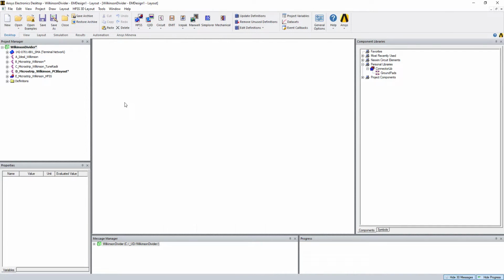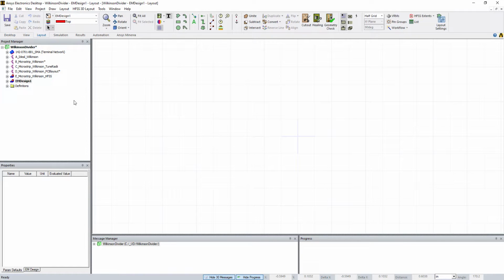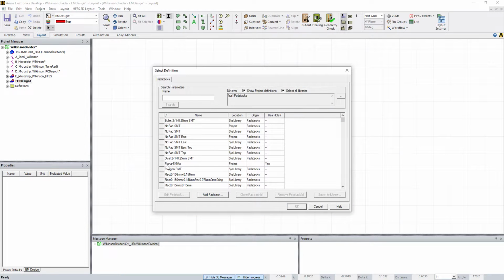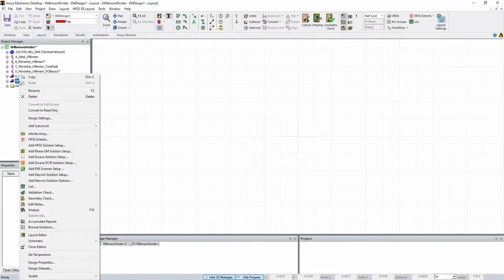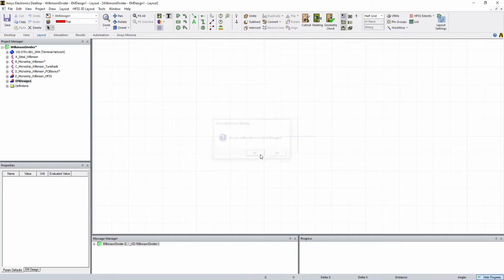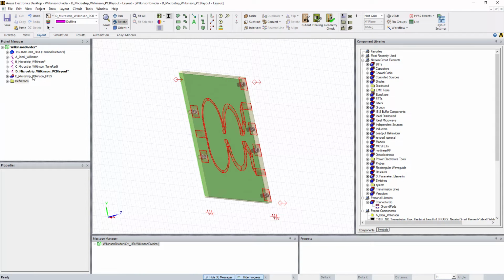And when you do that, I know it's kind of a goofy thing, but by doing that, if you go to layout and via style, it makes sure that this planar EM via is part of your project. You do that first, and then you won't have any problems. So let me go back to here.